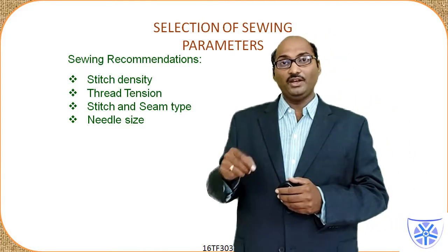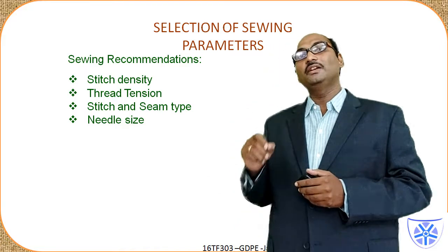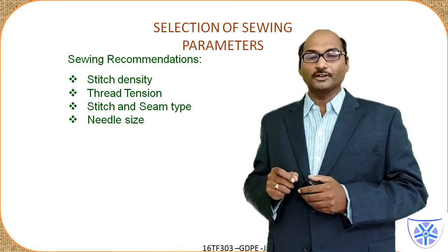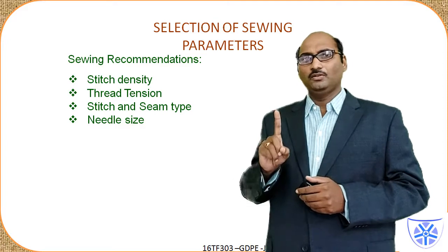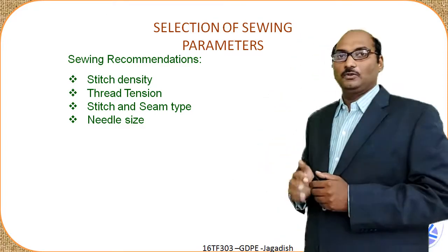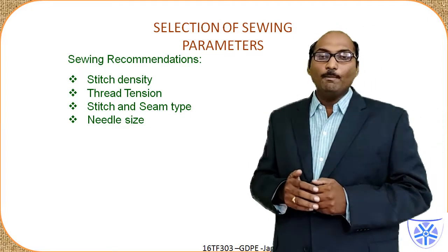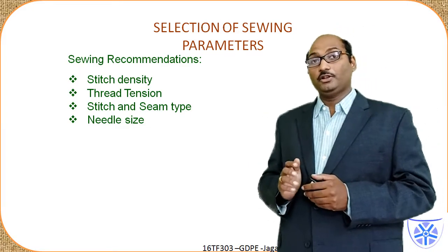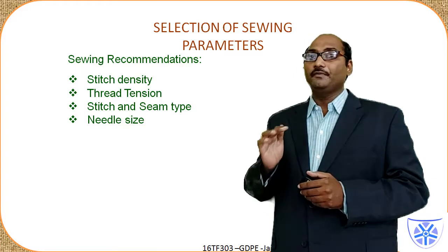When the SPI is very high, it will definitely cause a puckering effect. This is the first point. The second point is the thread tension. Thread tension should be comparatively lower.